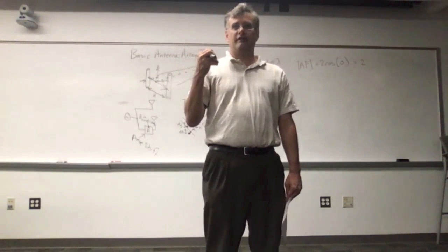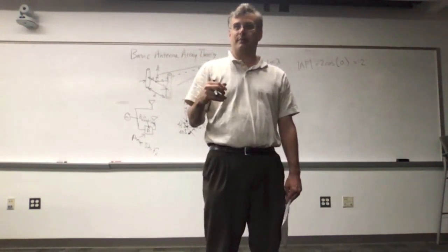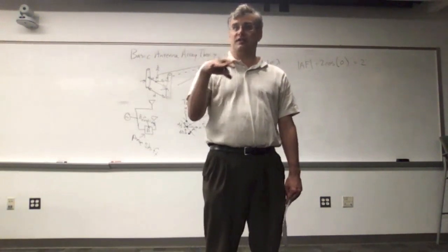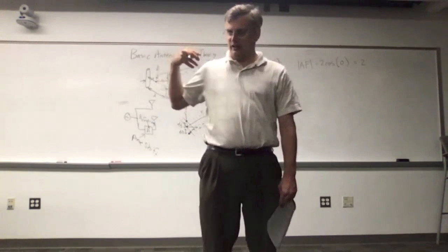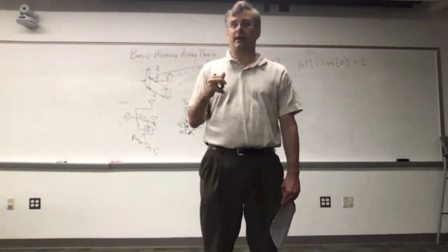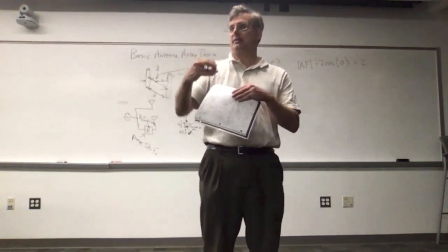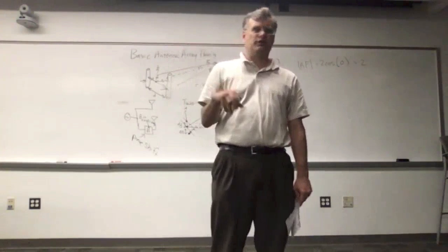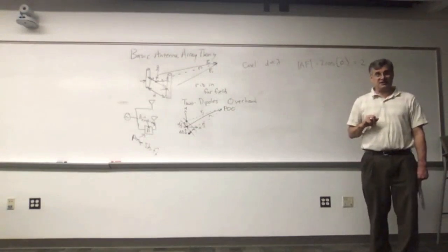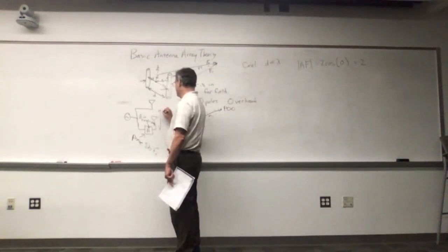What does that do? Well, if the mu is small, then the wave travels more quickly through the medium at a high velocity of propagation. If the mu is big, if you haven't biased in the magnetic field on the substrate and it's part of a transmission line, then the wave experiences the full mu sub r and travels at a slow velocity of propagation through there. So for the same length, the same physical structure, it will experience different phase lengths through the device. And there's all sorts of variations on that idea. So anyway, let's just pretend we had one of those devices in the system. Now we've got two variables to play with. We've got the phase and we've got D.